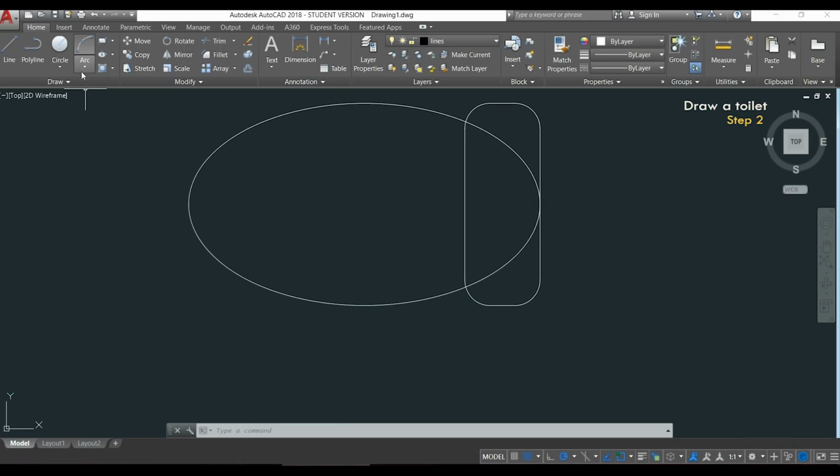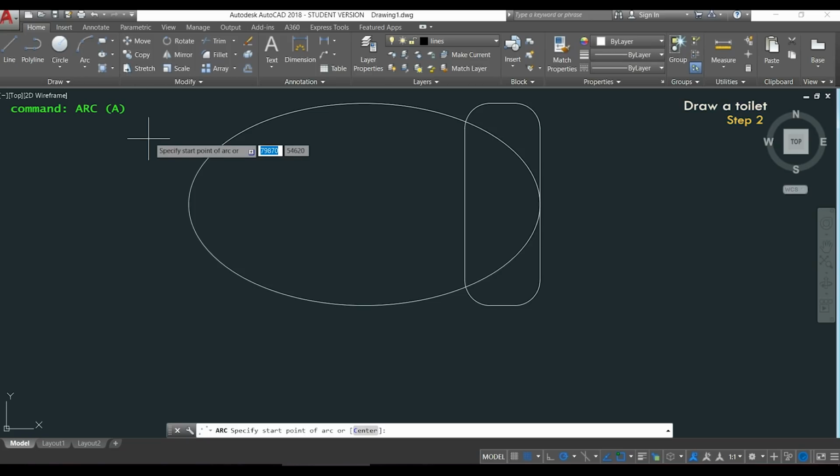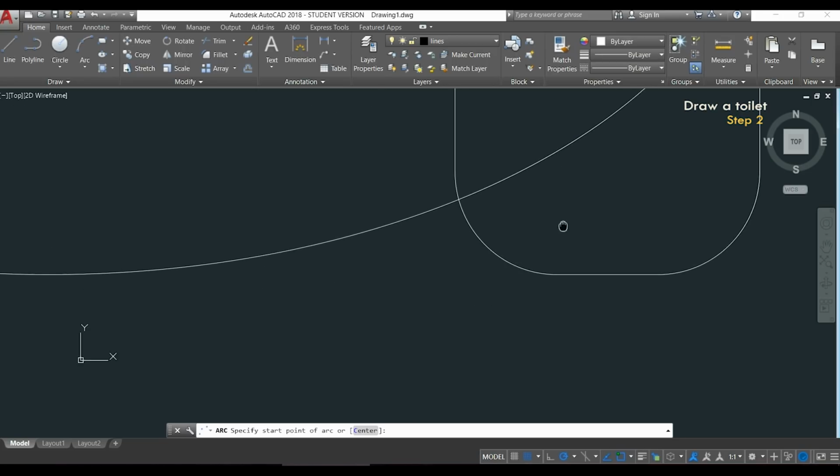Now, I'm going to use the command arc and choose the option 3-point. As you imagine, with this option I insert an arc by choosing 3 points. Now, the first point will be the intersection with this arc, around here, but it's getting hard to move the pointer. But I can solve this easily by switching off the snap mode. Look, I can move now without any problem.